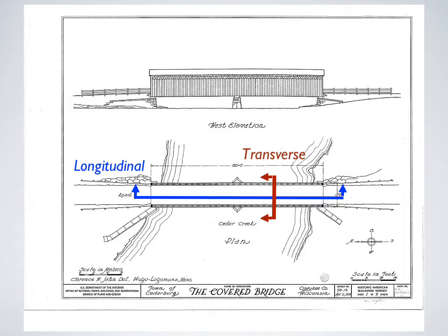When you hear or see a section on a set of plans, what they really mean is if you slice the project at a particular point, and in a lot of cases that's right down the middle, the section drawing will show you what the inside of that part looks like. Imagine cutting into a piece of cake and it exposes all the layers and the type of cake that it is. It's something you can't determine from the exterior alone.